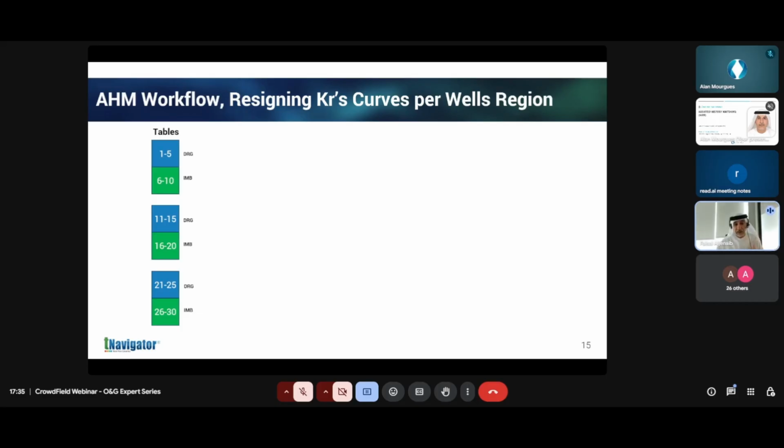I just want to change the relative permeabilities to accelerate or slow down the fluid movement within the model. So then I will need to create another set of the data. By editing, I observed my tables ranging from 1 to 10, the maximum. Now my next table will start from 11, meaning 1 plus 10, so it becomes 11 to 20. That's another set of data. I just take it and put it following the first table.